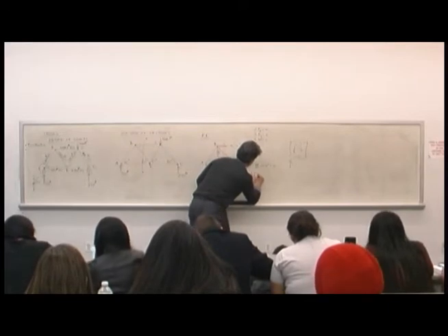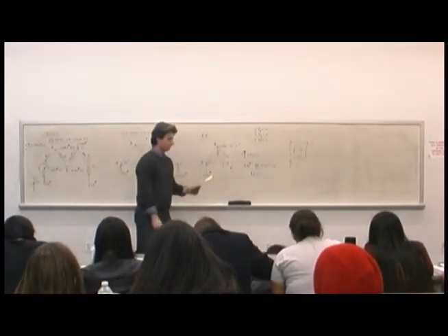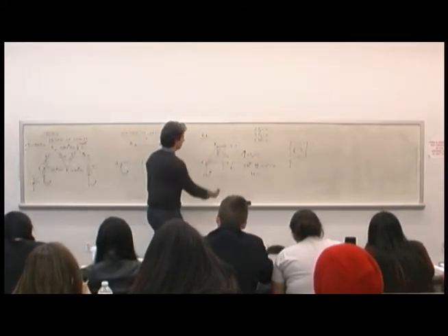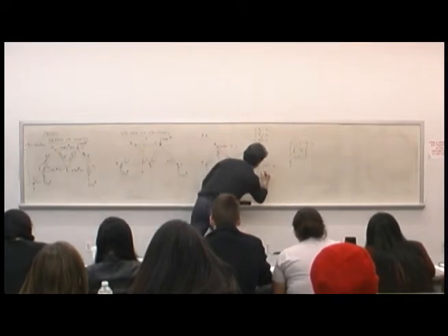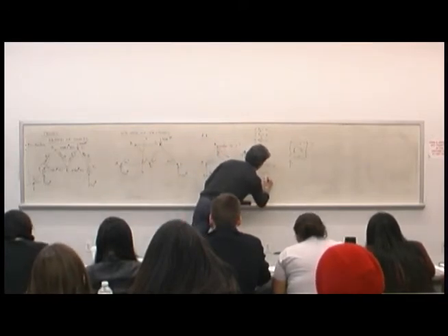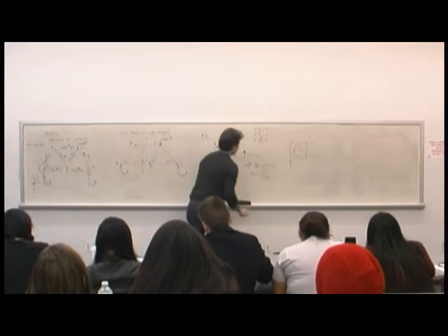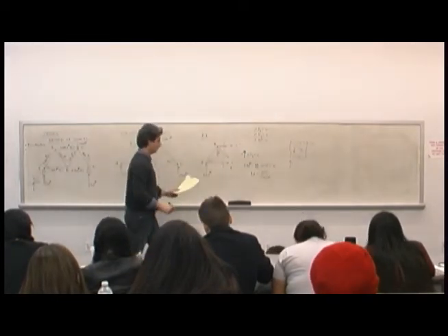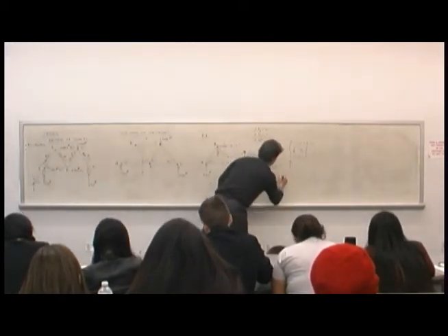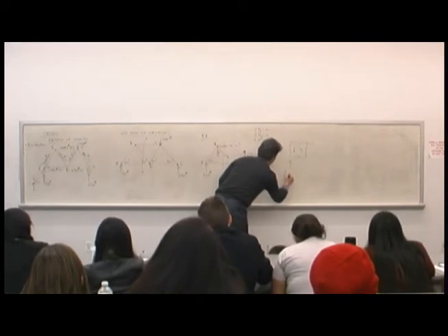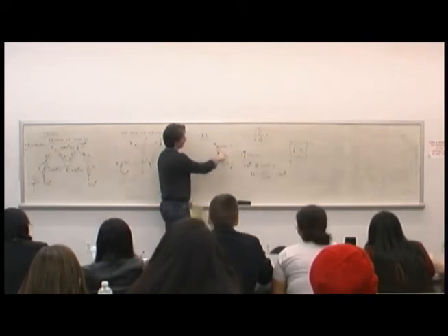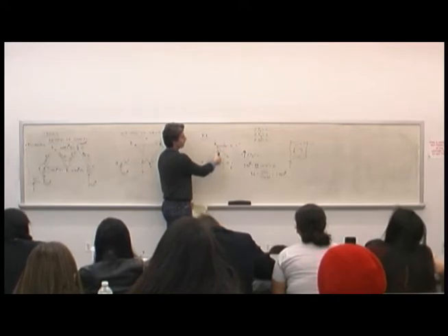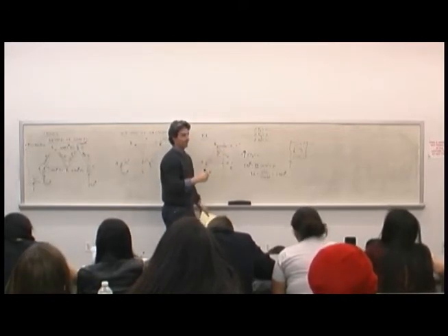So PE is what? 250, right? Put on the other side, 250 divided by cosine 30. What do you get? 288.7 pounds. And it's going away from the node. So is it compression or tension? Tension.